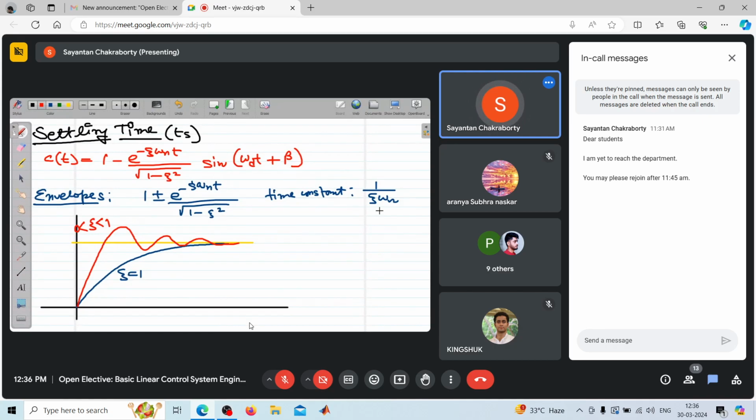So this is the initial position, and this is the final position of the robotic arm. It moves like this. The response should be that it reaches the desired position in the quickest time, but the other restriction is that it should never overshoot the position. Because if it overshoots, it will exert some additional force on the delicate legs of the pins, and they might get damaged. So it has to be precise and should not overshoot the final value.